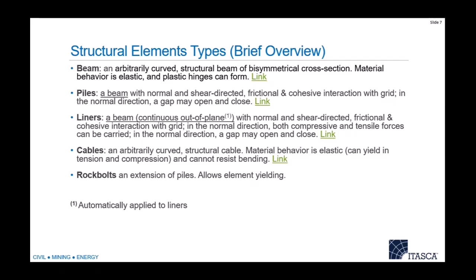So what we did instead was, a lot of our consultants needed a way for these beams to behave plastically instead of just perfectly elastic every time. So we introduced this idea of a plastic hinge where once it reaches the bending moment of some sort of bending strength, the node will behave plastically and just start bending in a plastic manner.